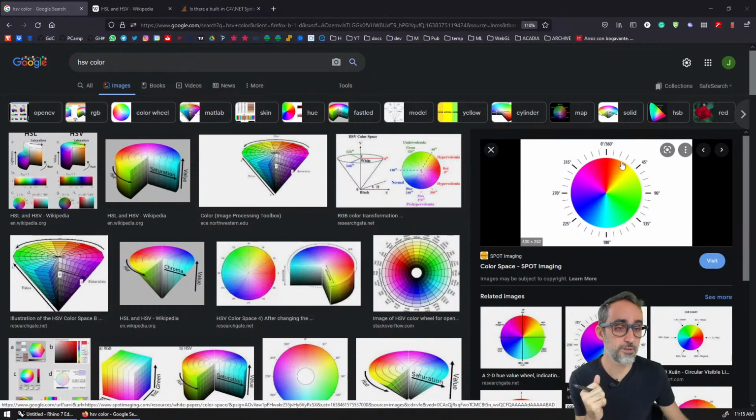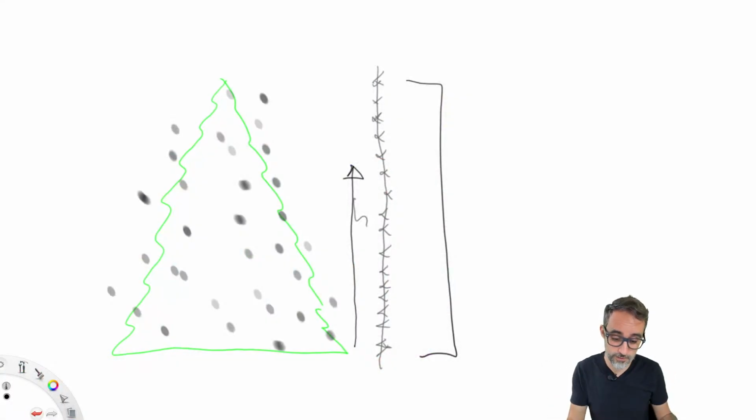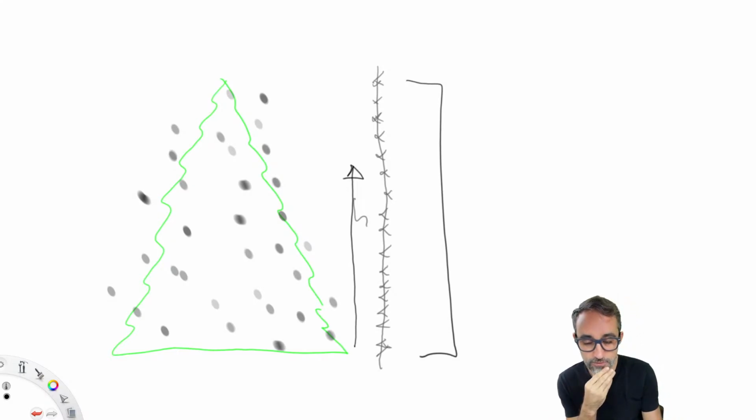So if we set a value of the color, for example, 45, we get yellow. But if we start increasing by 1, you can see how we transition from yellow to green to blue to a darker blue, etc. So working with one number that goes from 0 to 360, we can oscillate between different colors of the rainbow, creating a very nice visual colorful effect. Now we will eventually have to convert from HSV to RGB, but let's put that to the side for the moment. So the challenge here is to figure out over time which color from 0 to 360 each one of the LEDs is going to have.